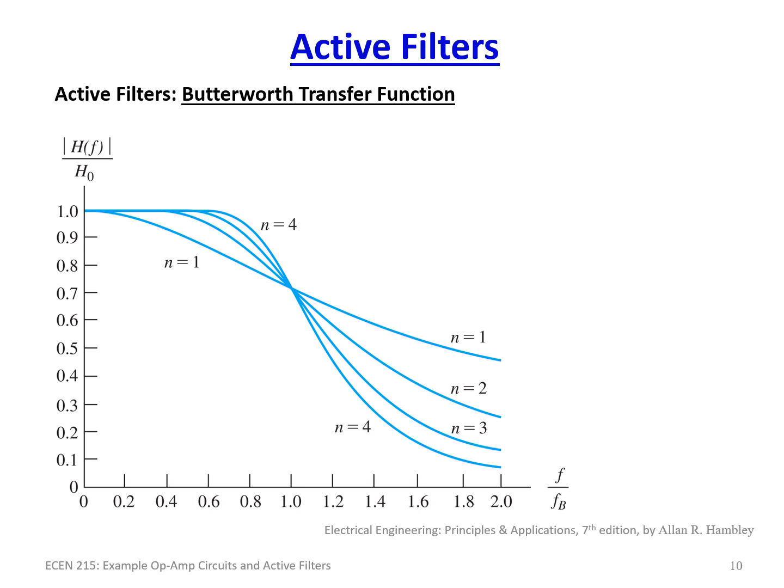There was a gentleman named Stephen Butterworth back in the 1930s who came up with a set of transfer functions dealing with low pass and, for that matter, high pass filters. This is known as the Butterworth transfer function, and it deals with various orders. We've been looking at an order of 1. An order of 1 has a very slow roll off, of 20 decibels per decade. That's usually fine for a lot of functions where you don't really care, you're just trying to get rid of general noise and things like that.